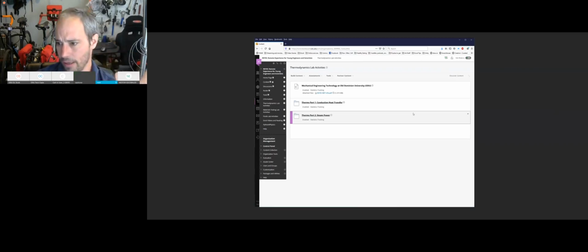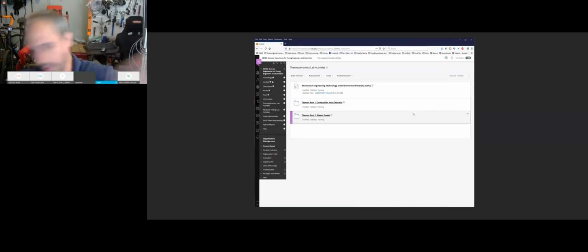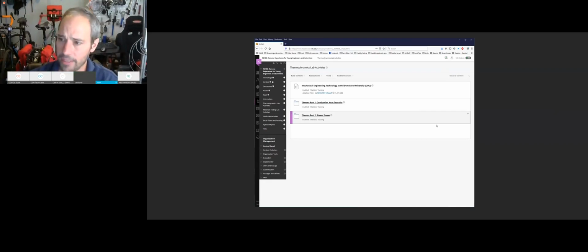An Ericsson cycle is very hard to do in real life. We don't really have them producing any power. They're very expensive to make happen, but they're very similar to a gas turbine cycle, approaching isothermal, approaching isentropic expansion and compression. Still not really there, or isothermal heat addition and heat rejection. Again, you look at it briefly in thermodynamics, but usually not very much, because it's not really a practical cycle yet.